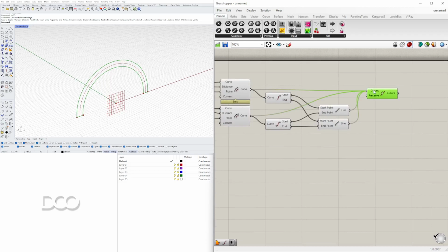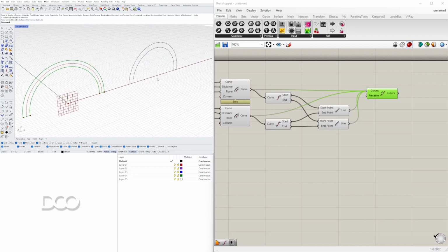And so now here at the end, when I hover over the input, it'll say 4 values, which are going to be those 4 lines. And then here under the output, it says 1 closed planar curve, which is great. When we go here now and I middle click and bake, when we select that line, I'll move it over to the side. And this is also a way that you can test or make sure that things are going correctly, right? If I would have selected this and moved it to the side and it was not joined, then I would be worried, because that's one of the things I wanted to do here on the script, is join that curve.